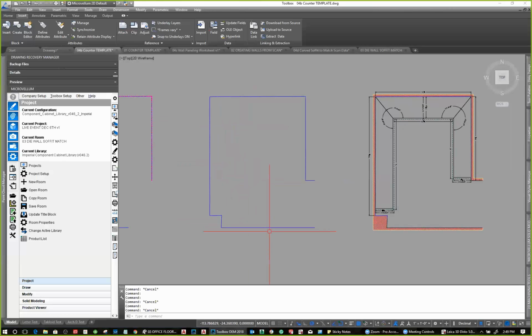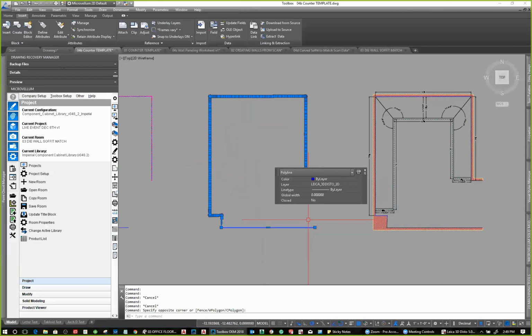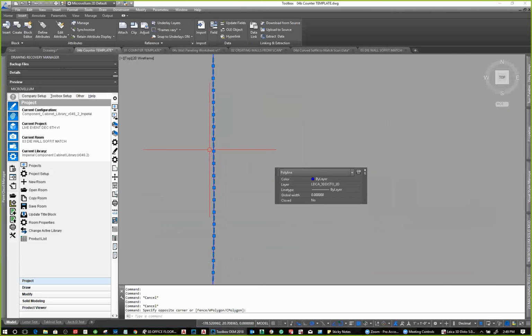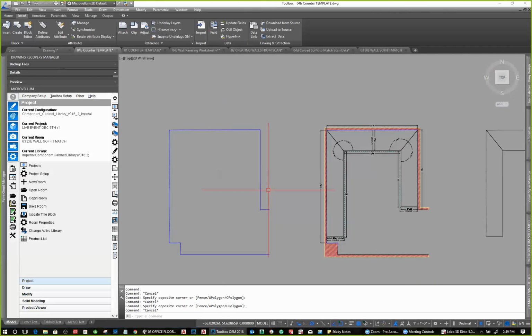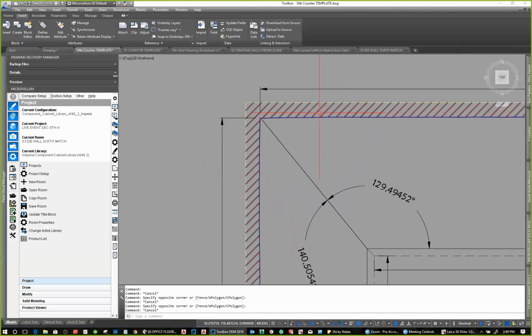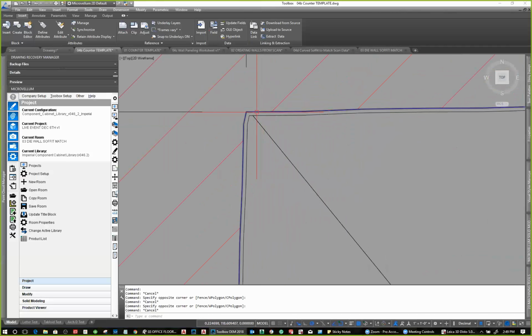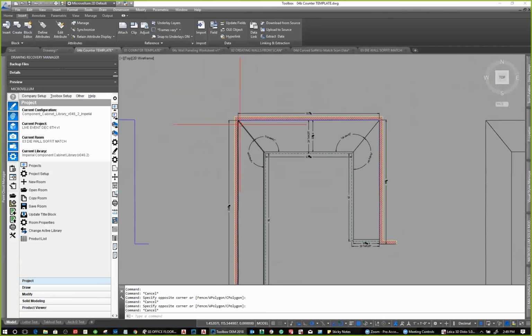I just joined all the points together and I created a polyline for the wall. And if you'll notice, on this part where the countertop isn't, I just use a straight line. And then on all the parts where the countertop was touching, I left the scan exactly the way it came off of the unit, other than filleting these to make them square corners. It was exactly the way it came off the unit. And then I took that and I basically offset just a 1/16 of an inch, because if you're tight, the countertop won't fit.